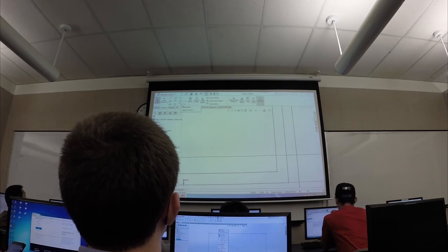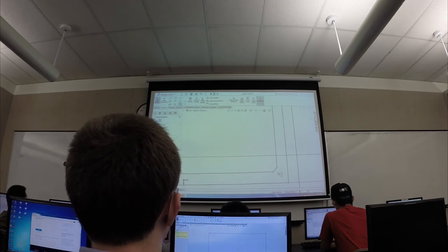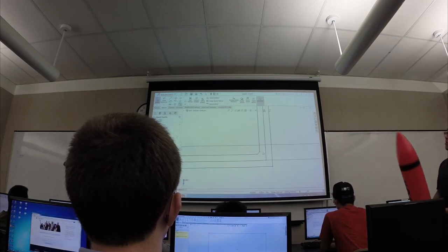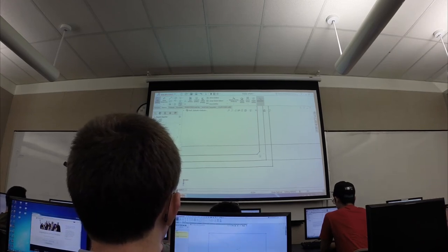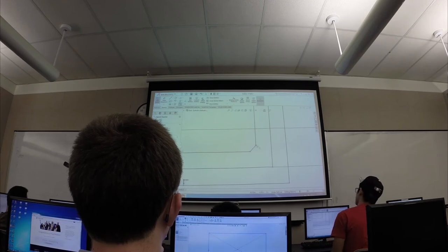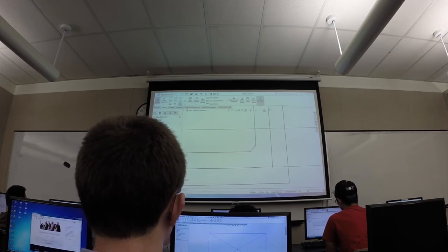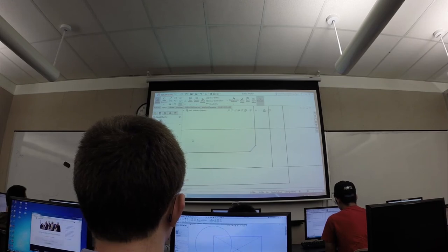So come here, drop-down menu, sketch chamfer, and when we select that, you see that it's not a rounded radius, right? It's just a diagonal. When you're doing a chamfer, you could define it in two ways. You could do a distance and distance. That means it will select a distance here to offset by and a distance here to offset by. If you have that equal distance button clicked, it'll always go at 45 degrees. But if you turn it off, you can start defining your own numbers. Maybe you don't want it at a 45 degree angle. Maybe you want it at something weirder.